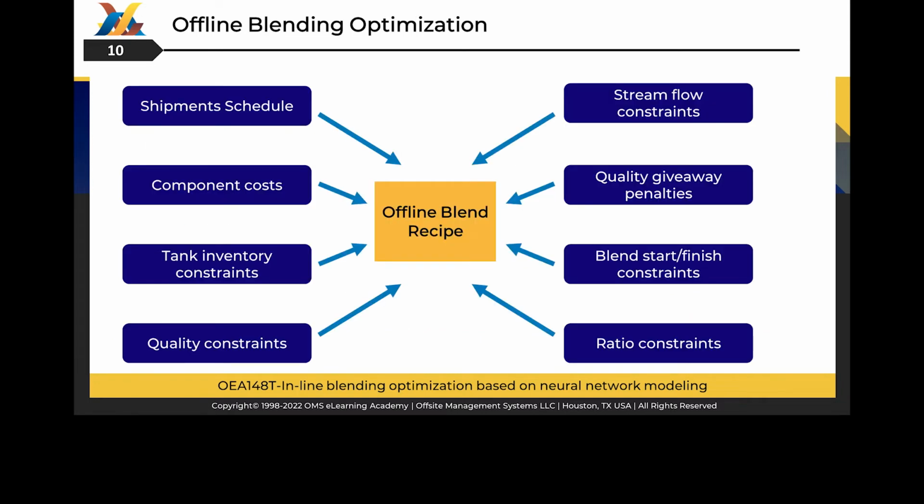Online blending is necessary, as no model can fully predict the properties of the intermediate product streams in advance, and specific real-time recipe correction will be necessary in all cases. The offline calculation may consider multiple blending periods. The online optimization searches for the locally optimal recipe in the vicinity of the recipe found by the offline optimization concerning the cost function. Complying with blend specifications may be a constraint for online optimization tasks.